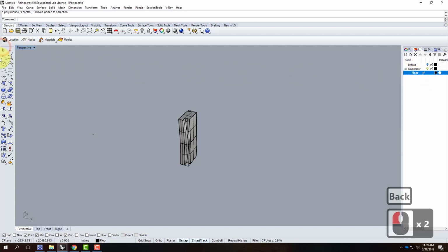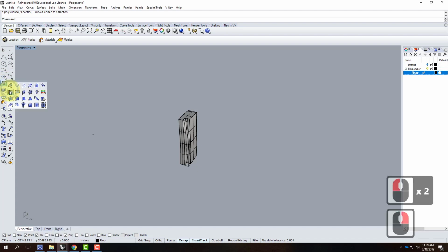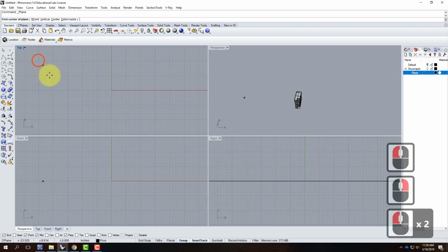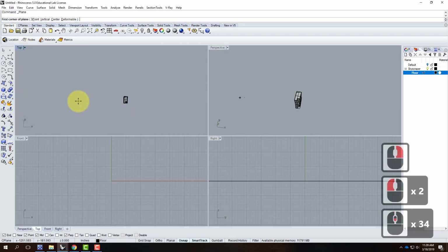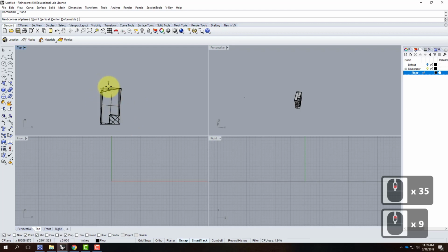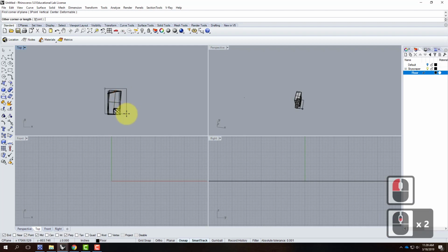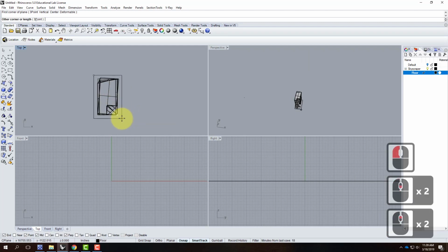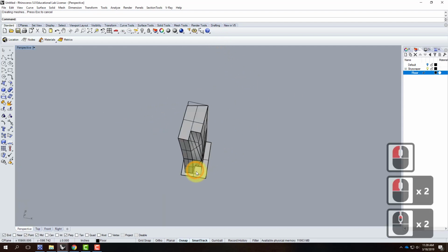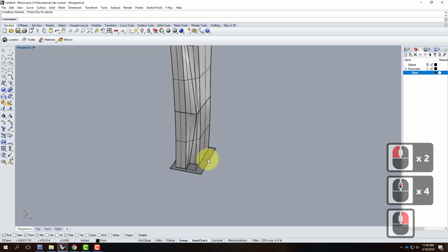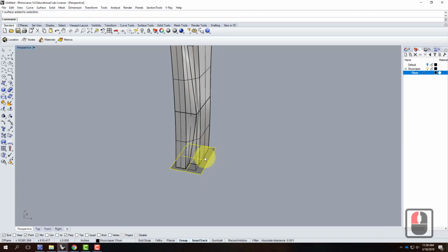I'll make that current, and I'll go ahead and establish a rectangle that is the size of the floor. Now, if I were to look straight down on my object, because it bends and twists a little bit, my floor needs to be a little bit larger than just that 100 by 200 feet that we started with. So I'll make sure that my floor is a little bit larger than my object. And there it is. Now, the first floor, we're going to have a little bit of a lobby down below. So it's going to be a 24-foot floor.